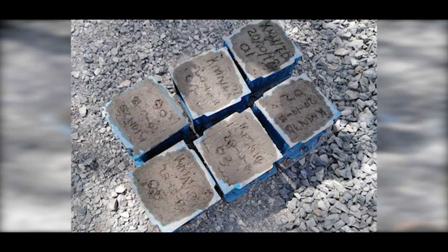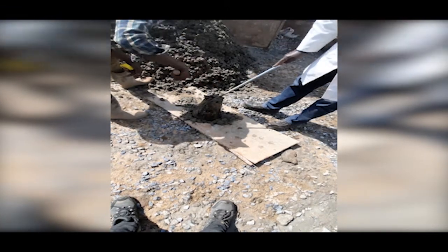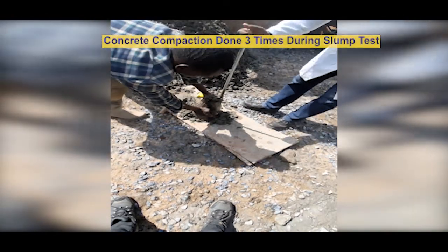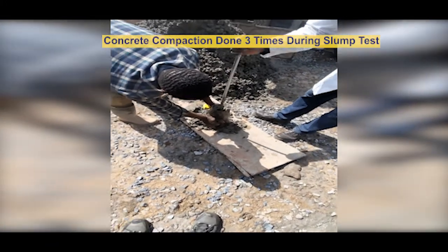The sure way of establishing whether the mix design was successful or not, of course, is taking samples during concreting. And the two typical ways we do this on our sites is by taking cube samples for compressive strength tests. That is where you take samples and test them for crushing at 14 days, at 21 and 28 days, so that you assess the strength of concrete. 28 days being the duration where you'd expect the concrete to have achieved 99 to 100% strength.